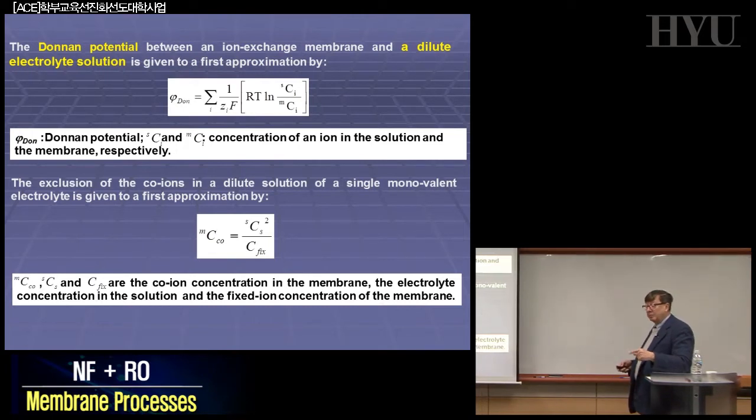Today, when we discuss blue energy, electrodialysis, reverse electrodialysis, we want to have a high power density of the order of 20 watts per square meter. The problem is that to have this very high power density, we have to work with very high salinity solutions. Seawater is not good enough. Instead of seawater, we work with brine. For example, seawater is 0.5 molar, 0.5 mol per liter, while brine can be 2 molar, 3 molar, 5 molar. So in principle, you have a very high power density.